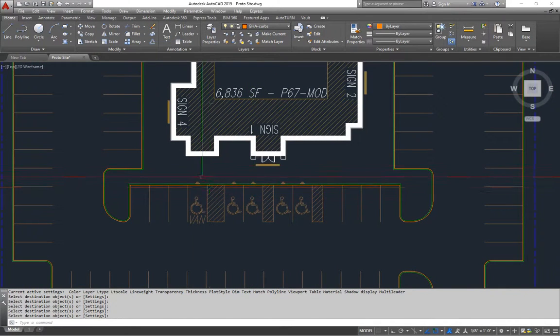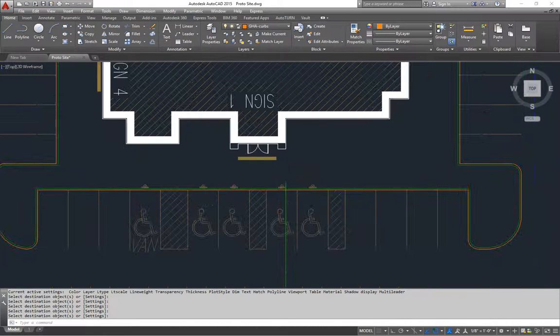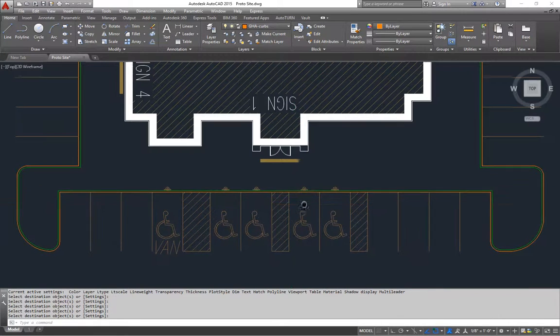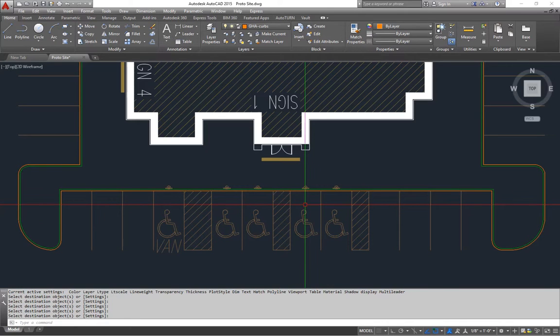what I'm going to do is, instead of trying to do ramps, and it ends up being like a skate park out in front of here, instead of doing ramps, I'm going to create a situation where the parking, we're going to say the parking slopes up 6 inches before it hits here. That way you can just roll right onto the sidewalk. And then in that case, you don't need ramps or anything like that. What you do need in a situation like that is some type of bollard or wheel stop to prevent cars from driving all the way up on there.